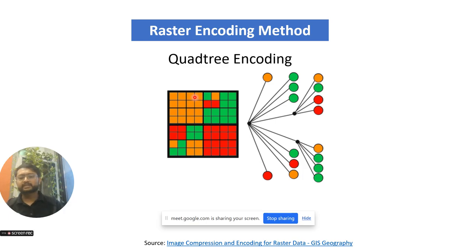Now, if you recall in the lectures, we do this process in three different steps. The first step is you have to identify GCPs. GCPs are ground control points, basically. How will you get to know that the image I am providing is exactly going to pinpoint at a given location? So I will identify some points in an image which are permanent in nature.